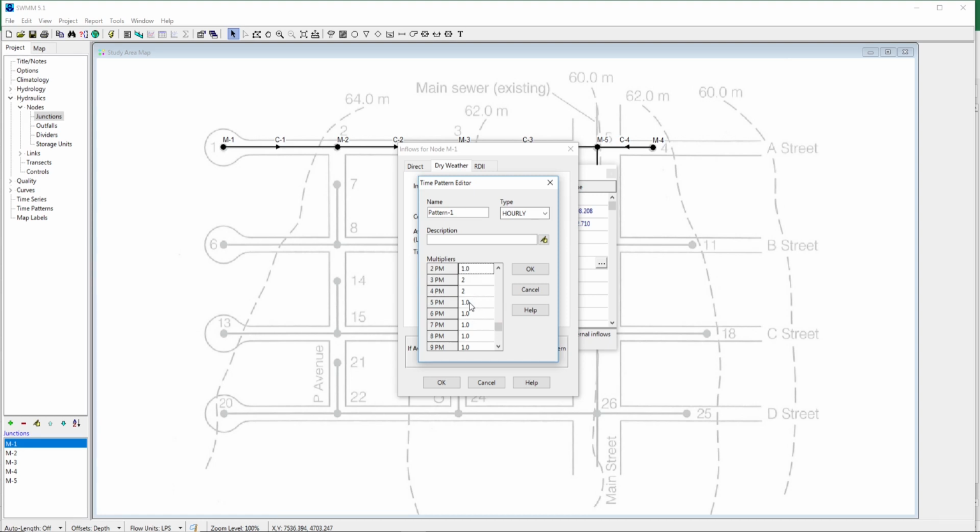So we have to be careful when we are setting up our own system of the demand or of the sanitary load pattern. We have to think that the average of this 24 hours duration must be equal to 1, because in 24 hours the average flow is being supplied, but during 24 hours sometimes it is more and sometimes it is less.